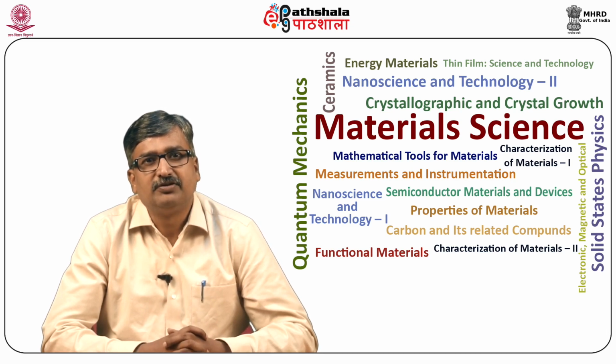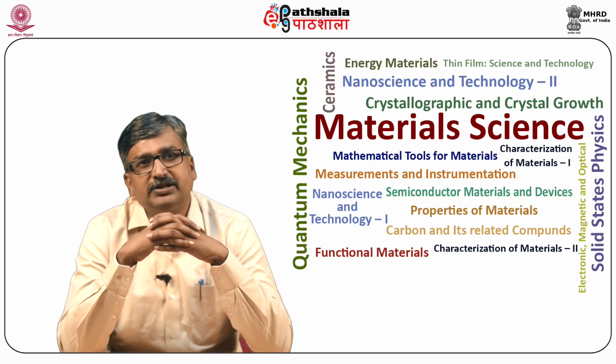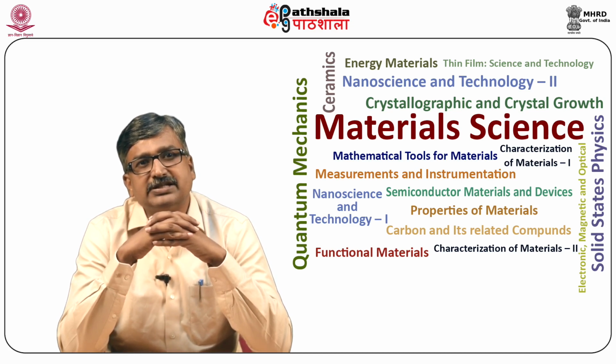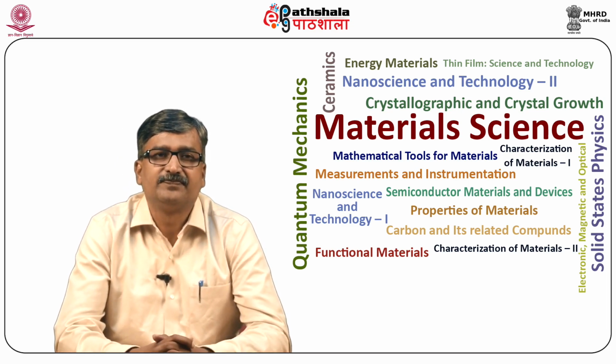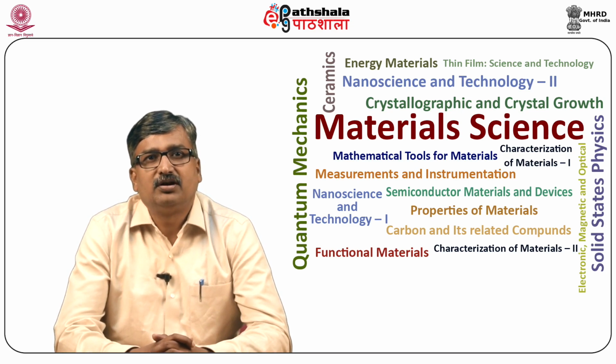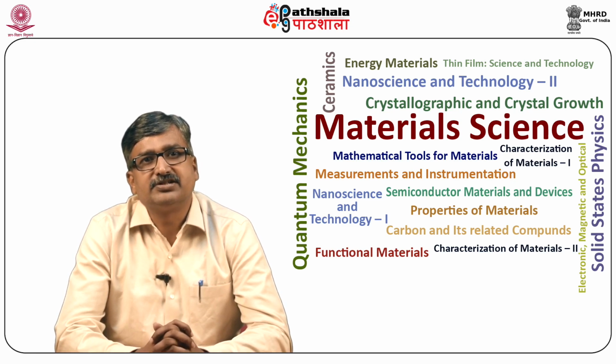Early in the century, when microstructure was revealed primarily with the optical microscope, it was recognized that refined microstructures, for example small grain size, often provide attractive properties such as increased strength and toughness in structural material. A classic example of properties enhanced due to refined microstructure, with features too small to resolve with the optical microscope, was age hardening of aluminum alloys.